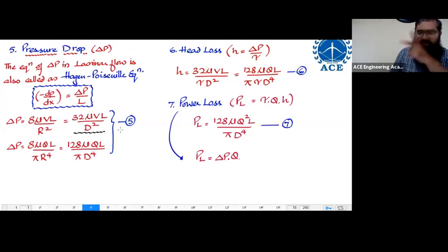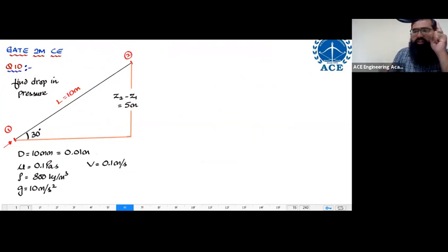Let me tell you what mistakes you have made. First mistake, that formula is not valid for delta P. That formula is valid for delta P star. Why? You are having a non-horizontal pipe.